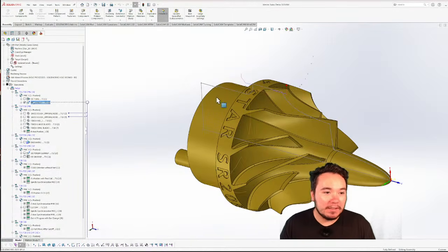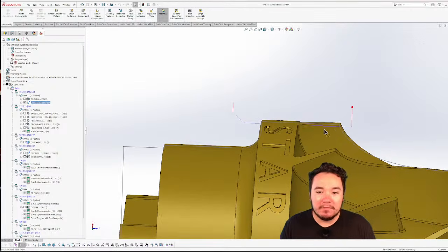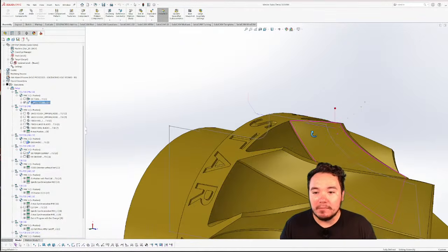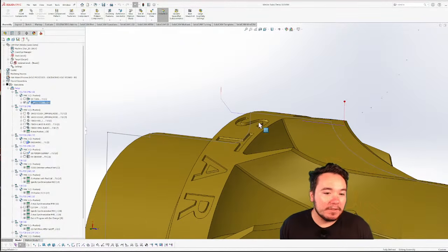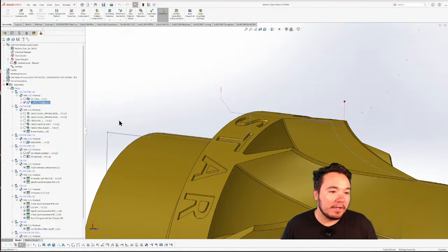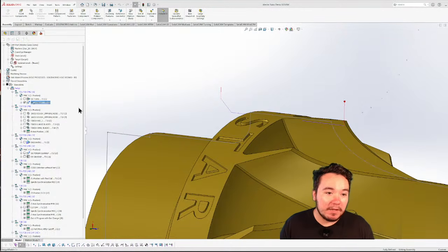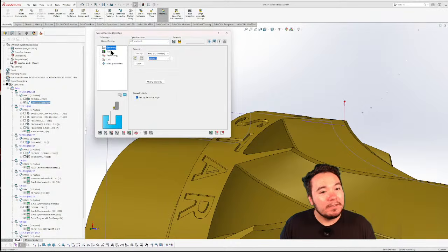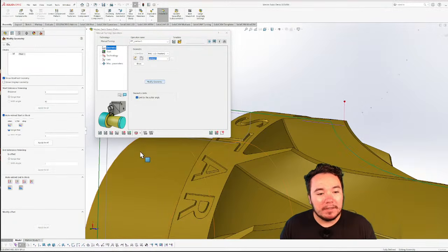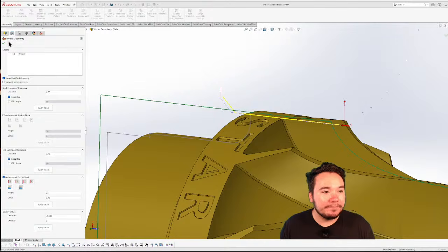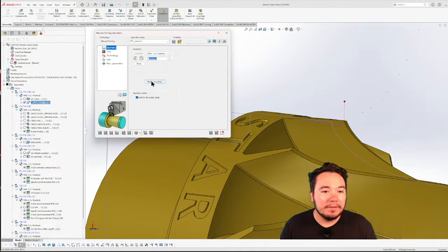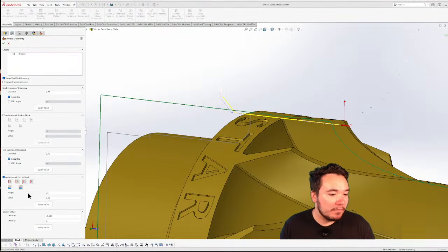All right, and then I did a manual turning operation because I'm going into the target model. Because we're using automatic updated stock in our turning module, I need to use a manual turning, and then I went into the geometry after just selecting this line right here, and I did a negative X offset, which allowed me to cut deeper than the target model, and just to finish the face after we did the engraving there.